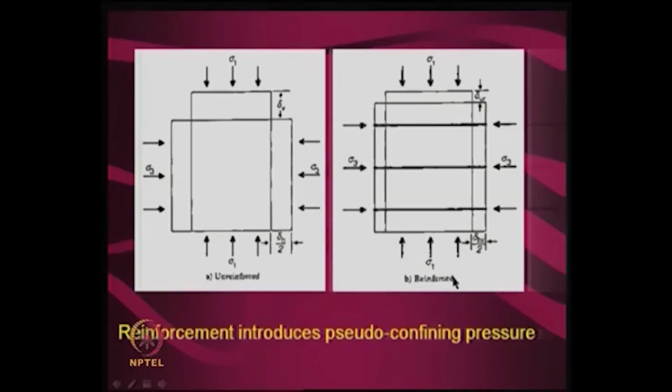So, he found that this is actually the origin of the reinforced soil technique, and as I just mentioned, he went back to the laboratory and perfected this technique. This is another small example. You put some layers of reinforcement in and you stand on it, and definitely it becomes like this. You can already see that his leg is embedded in soil, and they have equal height, weight, volume, everything is the same, except that here you have a reinforcement. You can see that it is able to support his whole weight, but here it is not. This is because the reinforcement element is taking care of the friction. I will just show you that.